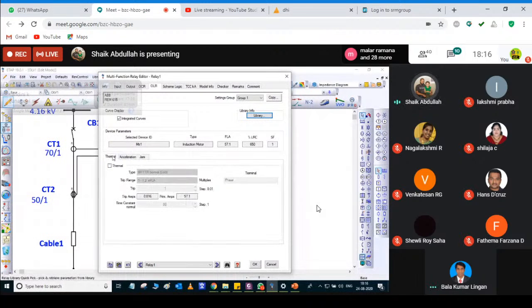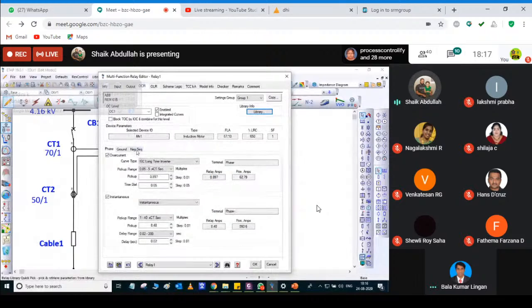This is not my topic here because these are all under unit protection, and even negative sequence is under unit protection. But for phase and ground, we have 4 operations: 50, 51, 50N and 51N. These 4 protection functions are widely called non-unit protection or backup protection of my motor.